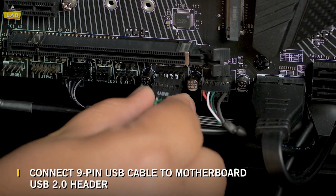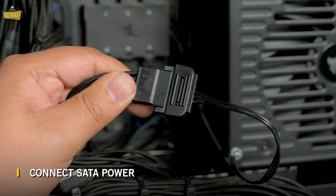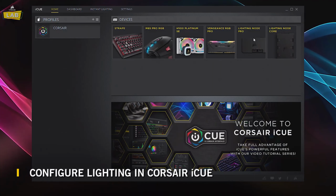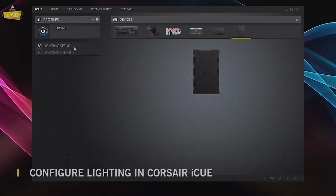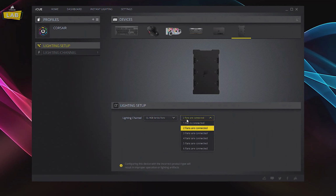Connect the USB cable to an available motherboard header. Connect the lighting node core to SATA power. Launch Corsair iCUE and click on the tile for the lighting node core. Click on Lighting Setup and select the fan type and number of fans using the drop-down menu.